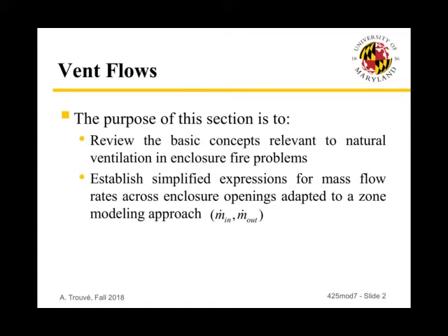We have the mass flow rate of air entrained from the lower layer into the upper layer, m dot a, that is required as well. And we have m dot in and m dot out, which so far we haven't talked much about, and that are required to describe the exchange of mass between the fire room and the exterior.